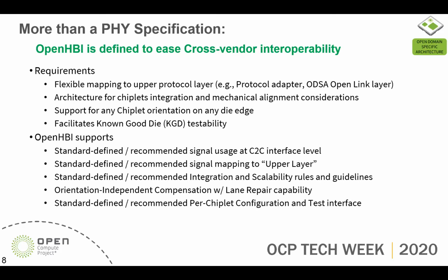So we defined the OpenHBI specification to include at least the following. Standard defined or recommended signal usage at the chip-to-chip physical interface level. Standard defined or recommended signal mapping to the upper layers. And then the integration and scalability rules and guidelines between different anchors and the chiplets. And the term anchor that is used, you may call it the host or SoC, but conceptually the anchor is the chiplet that can serve as a configuration master that can configure other chiplets in the packaged device.